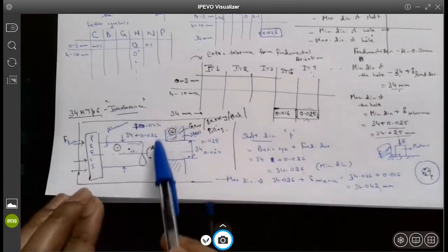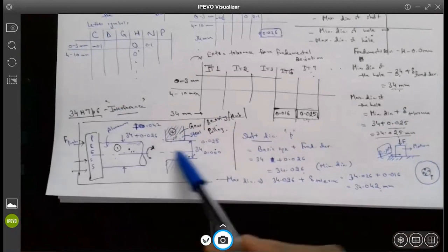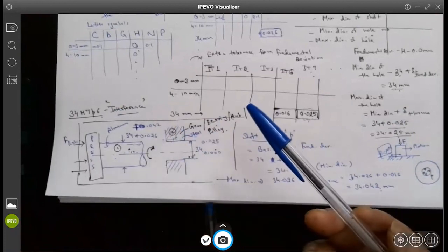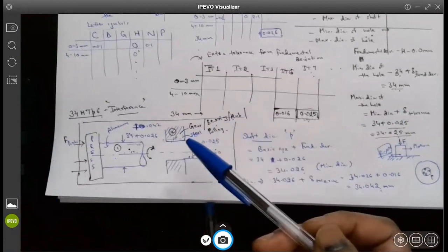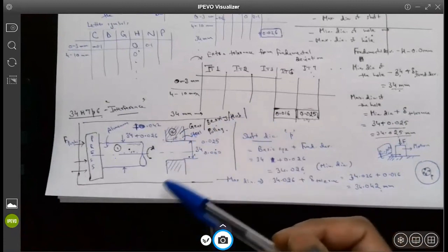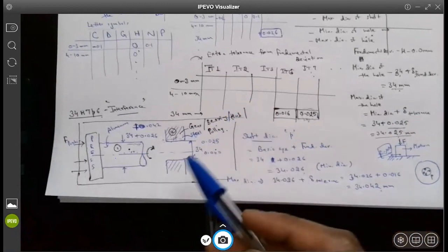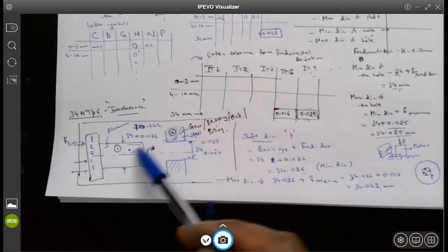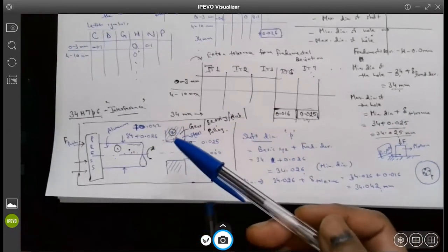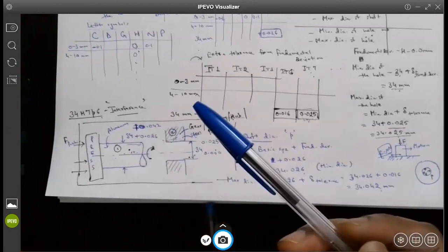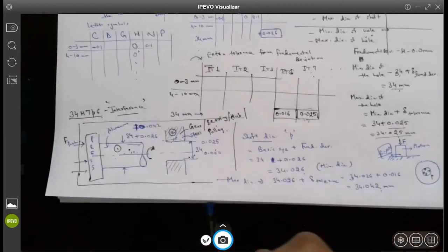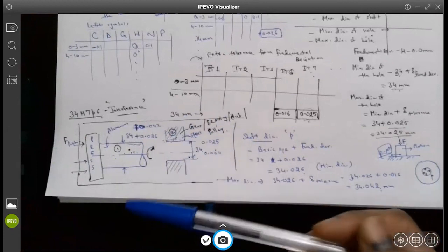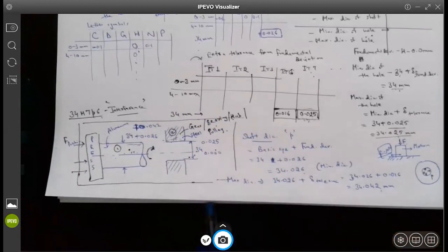If it is a clearance fit between shaft and gear, they will never move together, unless there is some pin, set screw, key, or some other way you are combining these two parts together. But if it is just interference, then how are you ensuring that the two parts do not have excessive deformation, they don't have excessive stresses, and there is sufficient friction for the torque carrying capacity that designers would like? So we will discuss this topic in the next lecture.